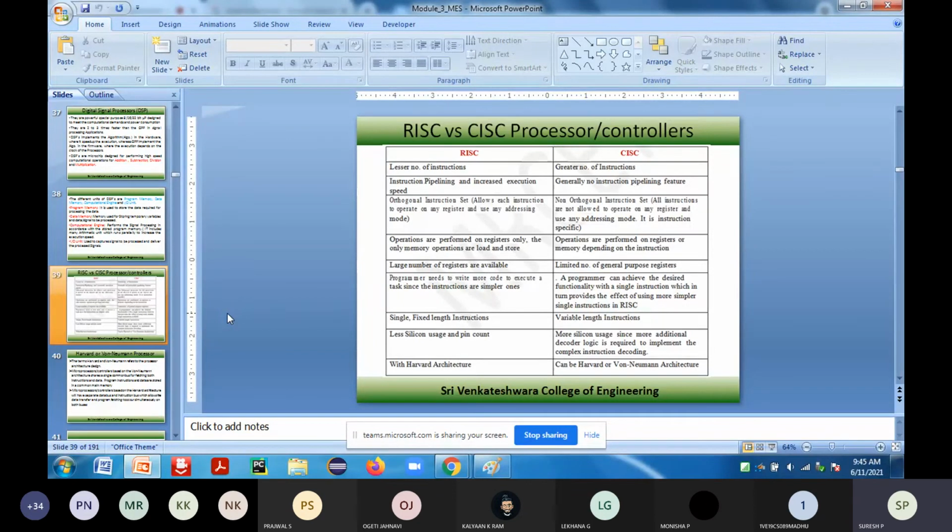There you have used the LHLD instruction. When you use the LHLD instruction, HL refers to the fact that it operates only on a particular register, the HL register. It cannot operate on any register. There are also instructions like load A, load B, which will load the data into the accumulator only. We are not specifying to load the data into a specific register.